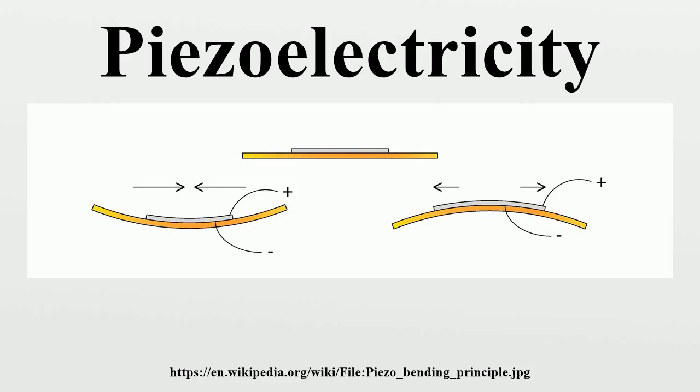The change in P appears as a variation of surface charge density upon the crystal faces, i.e., as a variation of the electric field extending between the faces caused by a change in dipole density in the bulk. For example, a 1 cc cube of quartz with 2 kilonewtons of correctly applied force can produce a voltage of 12,500 V. Piezoelectric materials also show the opposite effect, called the converse piezoelectric effect, where the application of an electrical field creates mechanical deformation in the crystal.